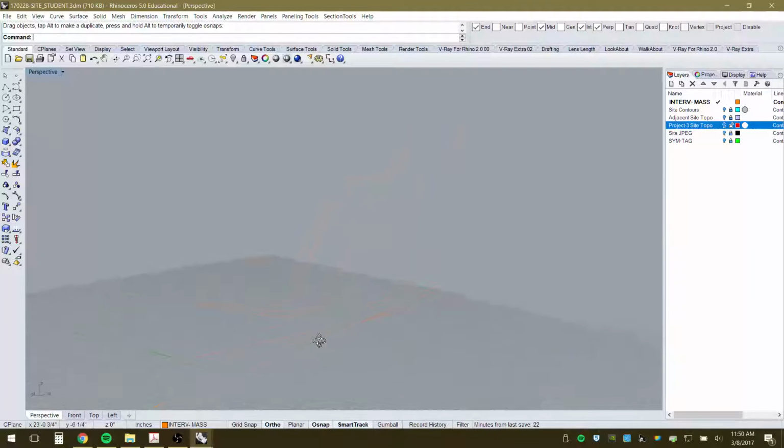Okay, so right now I'm just going to go ahead and loft these. Before I do that, I want to make sure that these are lined up. So I'm going to select this one and turn on its control points, and grab that control point and line it up with the end of this other. It's still a little twisted on itself. This will be a problem for creating a solid later on, so I'm going to go in and tweak that.